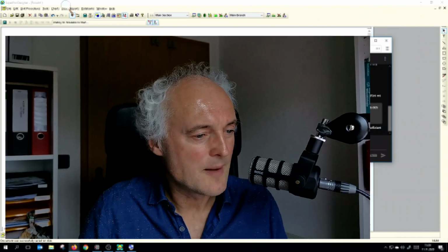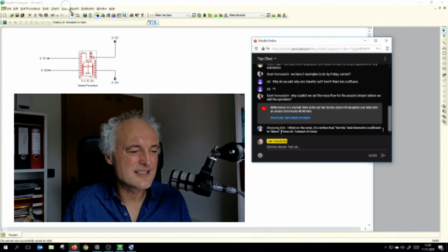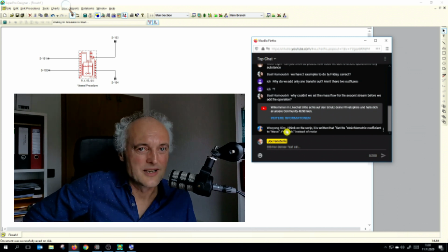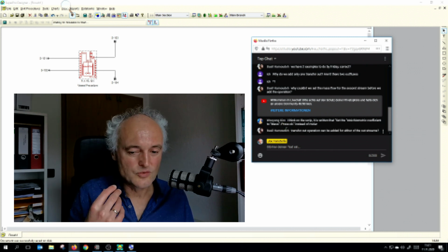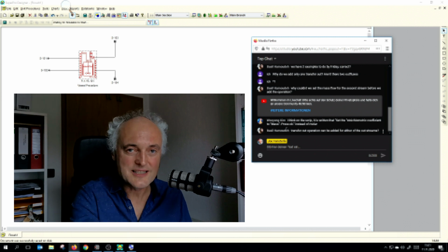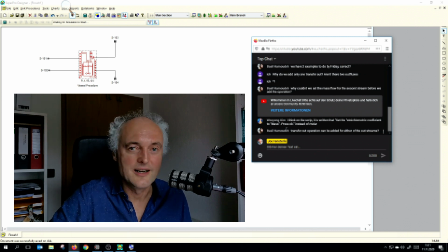Okay, set the same to mass. Yeah, okay. So the reason why this is written is because this was the old exercise. Don't set it in this case. Go for stoichiometric coefficients. In general, you would go for masses. So most processes and so on, you use masses and not stoichiometric coefficients. But in this case, it's a pure chemical reaction. So stoichiometric coefficients are easier.